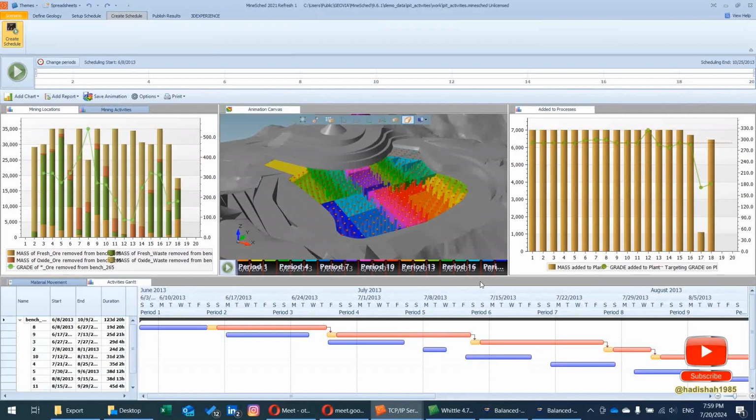Well, you are asking about haulage simulations. The simulator, and I'd better say simulating software packages such as HaulSim, are based on discrete event algorithms, and their task is to simulate what is going to happen during each cycle of loading and haulage, as well as considering other events such as the pit block because of blasting, or the queuing events because of a motor grader that is passing through the main ramp system and causes a decrease in the traveling speed of trucks, and so on.